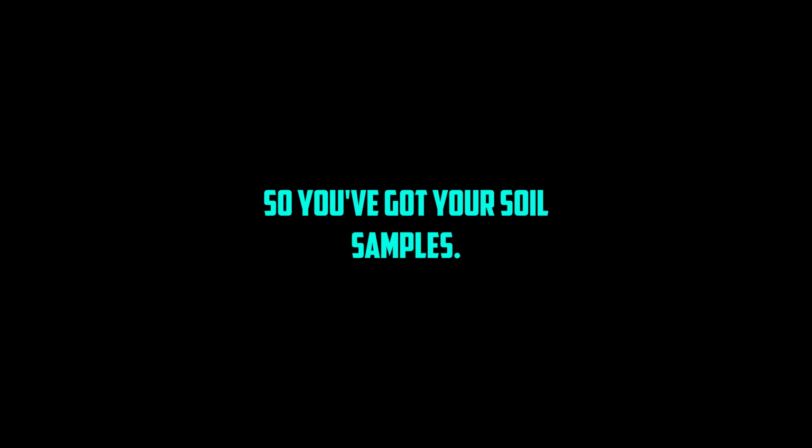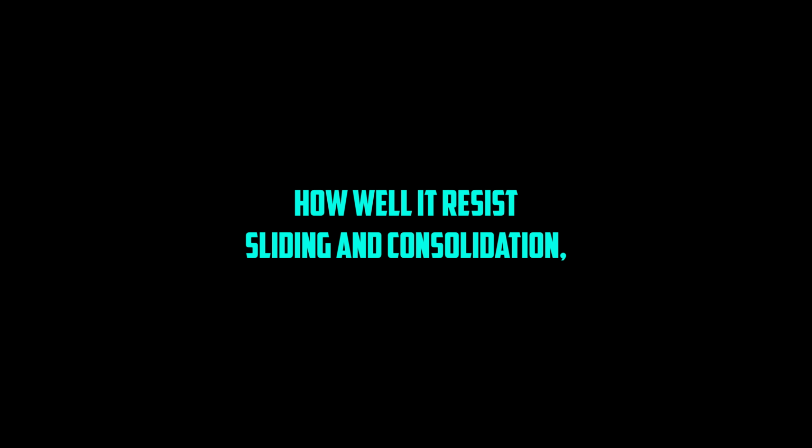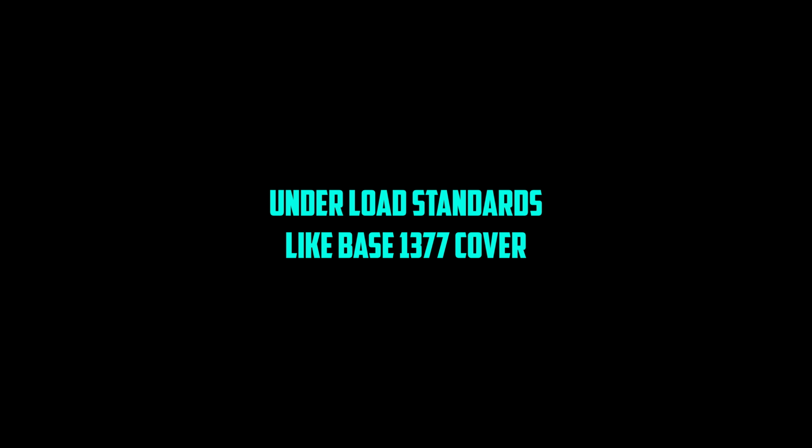So you've got your soil samples. What happens next? Assessing them. Right. You need to classify the soil. Is it clay, sand, gravel, silt? Grade the particle sizes, and then test its properties like shear strength, how well it resists sliding, and consolidation, how much it compresses under load. Standards like BS 1377 cover all this.